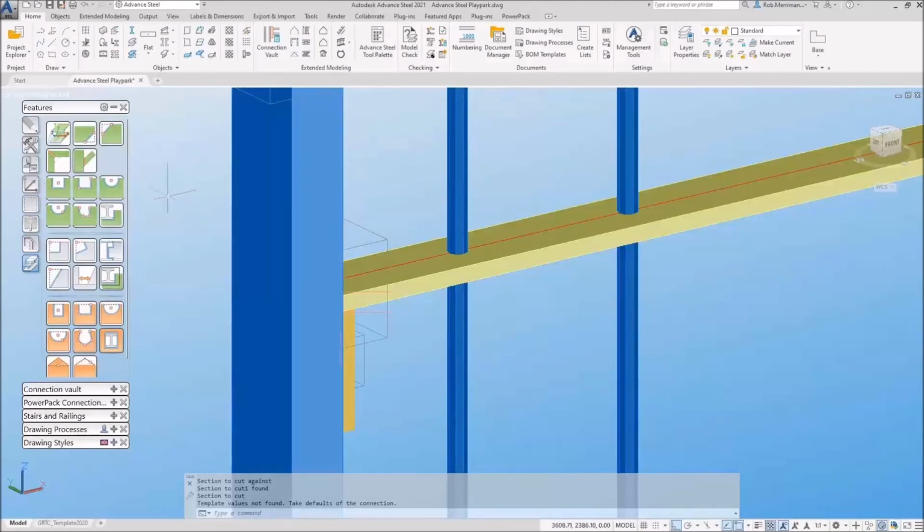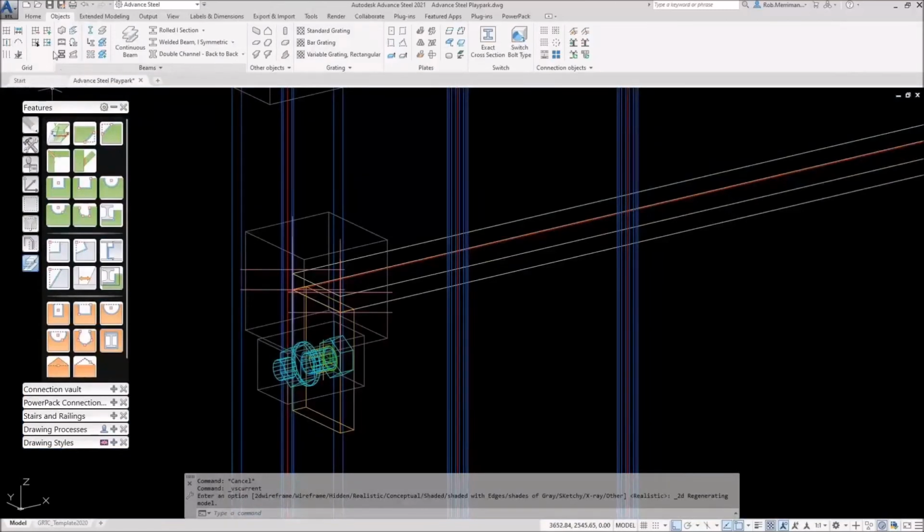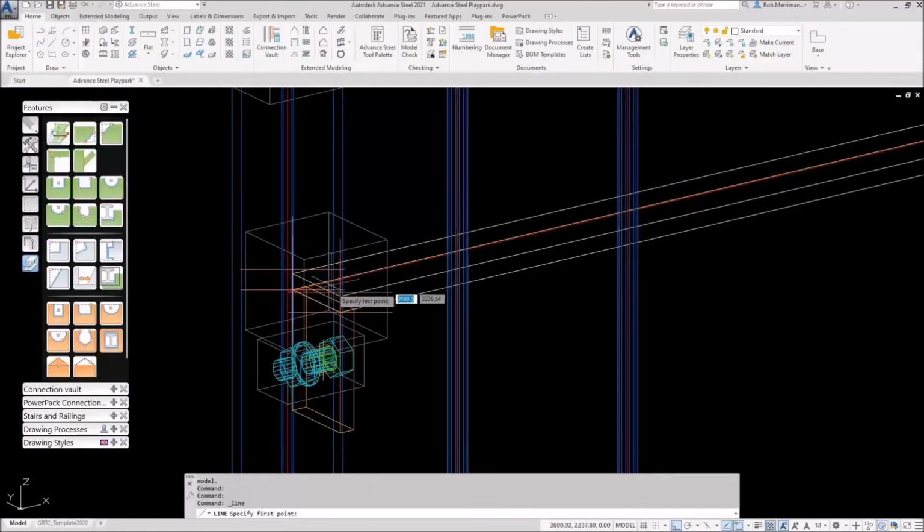If they're going to be drilled, and remember this is a flat bar, so we're running an NC file for this, we would use a hole by toggling our switch here. If they were going to be done with a laser profile and you want to contour, we would use a circular contour based on a center point. So again, just find out from the workshop how they're making it, because holes and contours are displayed in different ways in an NC file. So I'm going to do mine as holes.